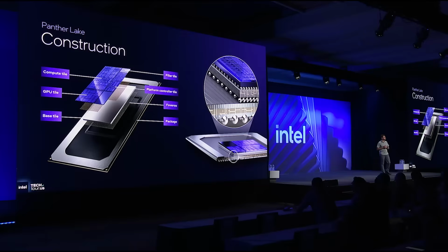Now let's look at Panther Lake's modular tile-based construction. At the center, we have the compute tile, with most of the computing elements and the memory subsystem. Next to it is the GPU tile with the graphics engine, which has been separated from the compute tile. We use the separation to scale the graphics tile independently from the other tiles, delivering the required graphics performance per segment.